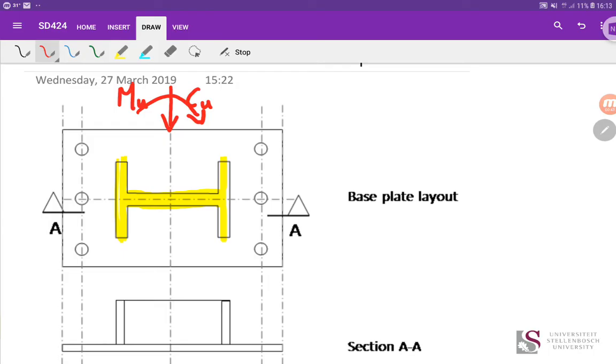where we can safely give a base plate thickness, because the most important thing as a designer, you would have calculated your moment and your compressive force from your structural analysis, and now you get to the place you have to answer the question now, how big is my base plate and how thick, what size bolts do I need? What size holding down bolts do I need? So we're going to start working on this.